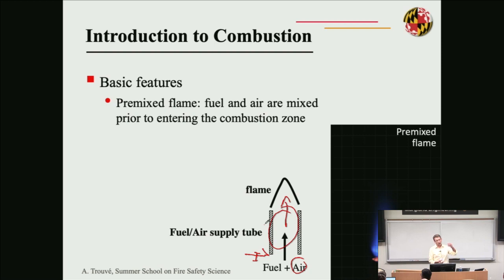If the tube is long enough, then this mixture is perfect, is homogeneous. And then basically, you have a flame that is supplied with a well-mixed stream of fuel and air that have been premixed prior to entering the flame zone. So this is premixed combustion. And these combustion events are not the dominant event in wildland fires, but they are responsible for some aspects of wildland fires. In particular, premixed combustion is important for ignition.